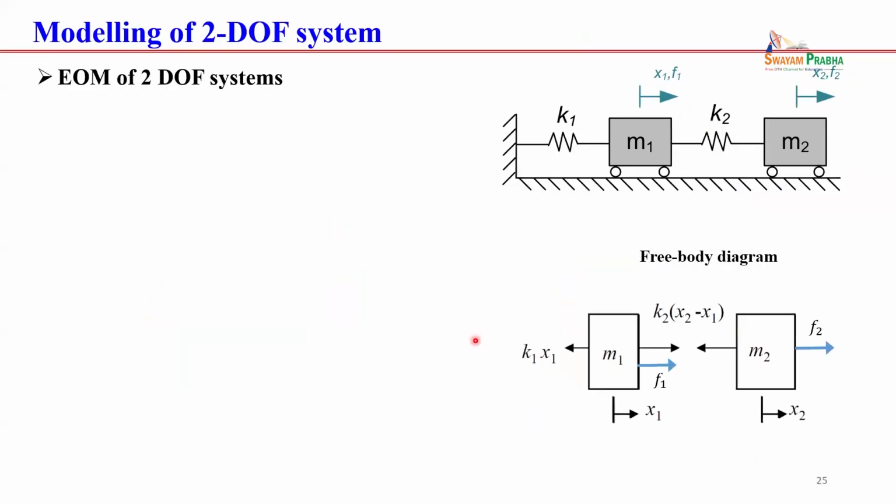So now, this is a typical vibration system, right? You have spring, mass, damper, with this link in between. This is a 2-degree freedom vibration system. For each mass, you take it out and draw a free body diagram.